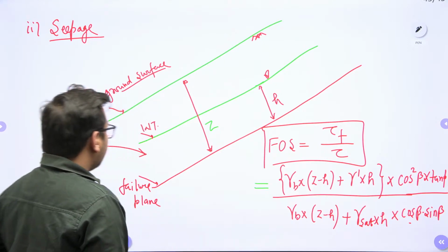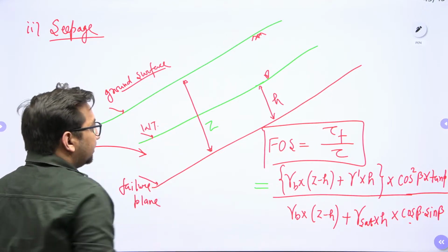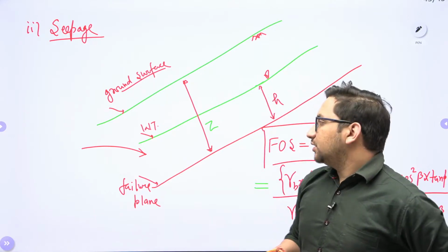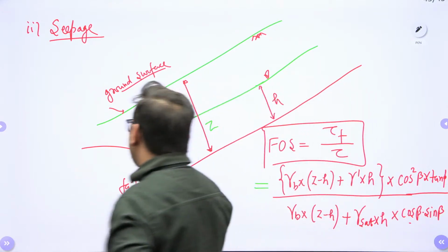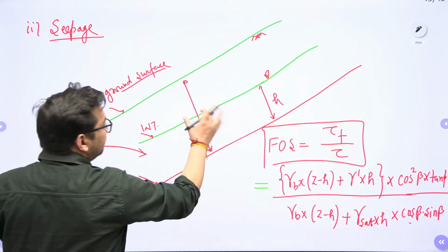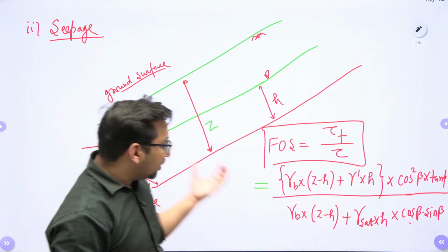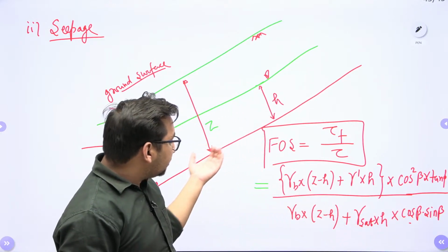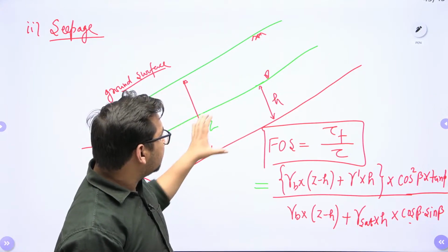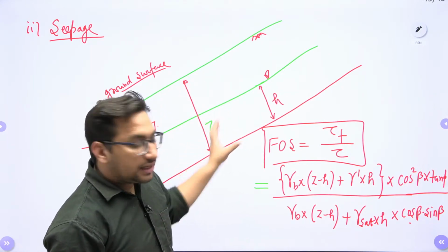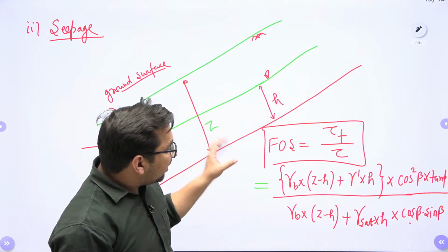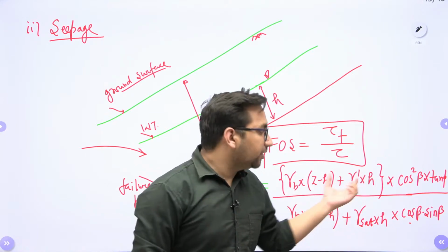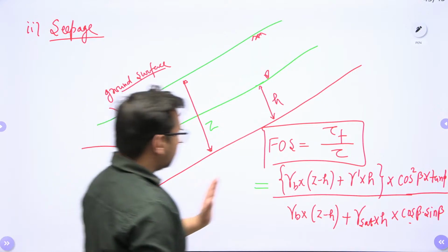You can calculate the gamma for this soil as gamma average, right? When you are calculating that gamma average value, first take this soil as saturated soil, as we have to use the saturated soil weight in the denominator. So, I can calculate the gamma average considering this soil to be saturated, and to use that average gamma, I can just subtract the weight of water in the numerator, right? So, we can also take it like this.